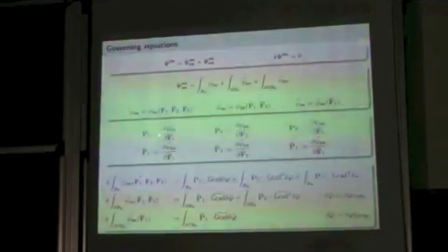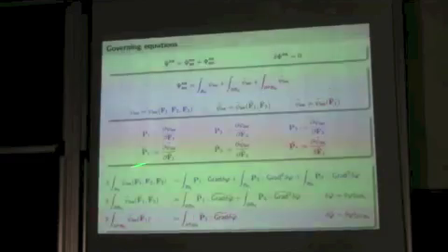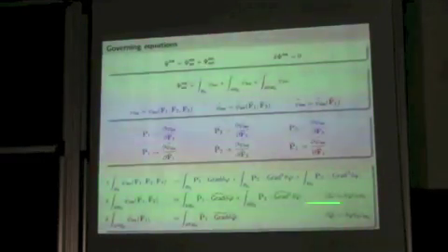For going further, we do this assumption. This is geometrically nonlinear, so I'm using this P. It's like a polarized stress or generalized polarized stress, not Cauchy ones. So P1 would be the derivative of the bulk energy with respect to F1. P2 is the derivative of bulk energy with respect to F2. And like that, for the surface, we do the same thing. And then there's variations of the energy. It can be nicely written like that.